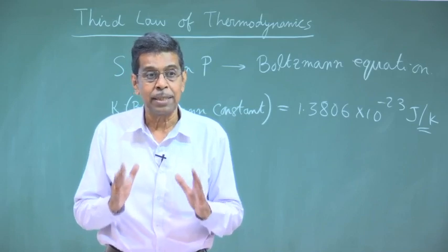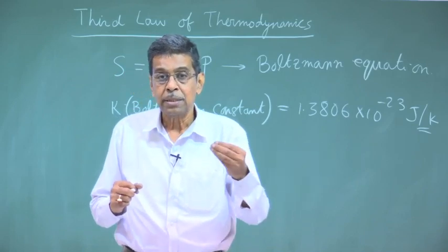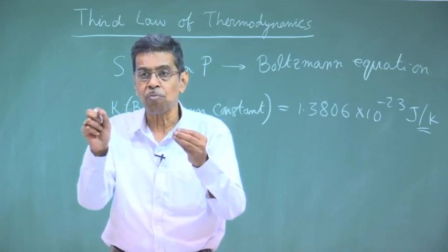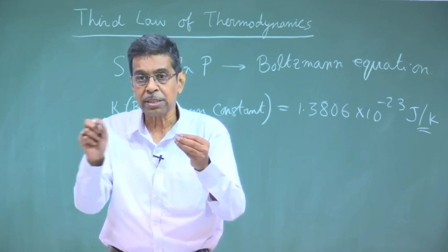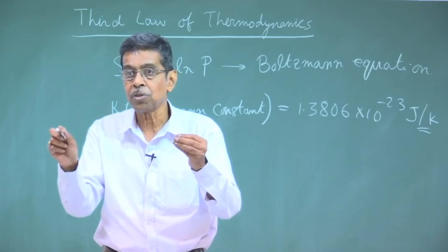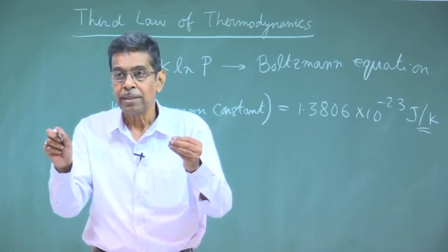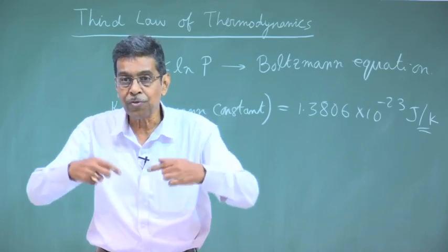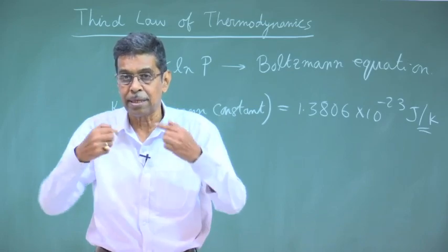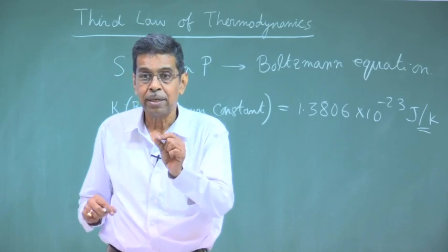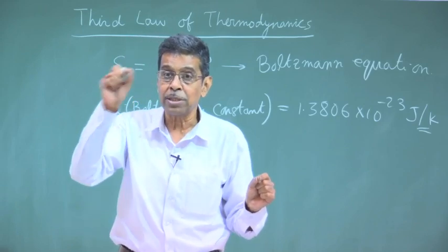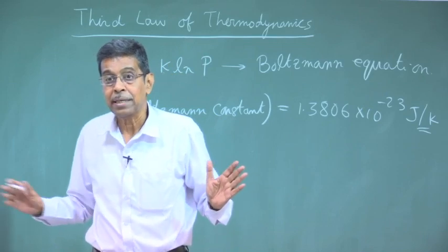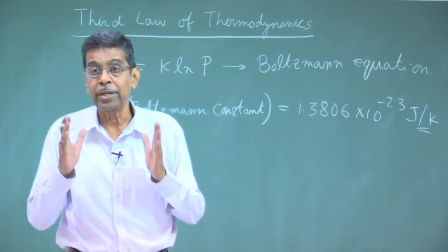Joule-Kelvin effect is like this: if a gas at a high pressure and temperature is allowed to pass through a small restriction or constriction, where there is a pressure drop because of mechanical friction, then it is found that the temperature of the gas decreases, if we isolate the entire constricted system, provided the initial temperature is below a certain temperature known as the inversion temperature. I am not going into those details. That is known as the Joule-Kelvin effect.